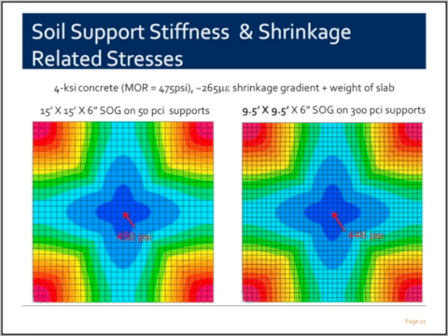And you can do several things other than just decreasing your joint spacing. You can use shrinkage compensating concrete construction. You can reduce the amount of shrinkage in your concrete by mixture. Todd will talk about that. You can use post-tension concrete to pre-compress it so it won't crack. Or you can use reinforced concrete, obviously. That's always an option to minimize the crack width and its consequences on the operations of the building or structure.